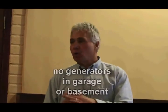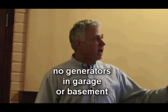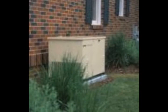Old school, generators in the garage. Generators in the basement. New school, no good. These items generate carbon monoxide. So it would not be a good idea to have it in or around any dwelling, obviously, where there are inhabitants. If you have a detached garage or a shed, not a problem. A basement, no, not a good idea.